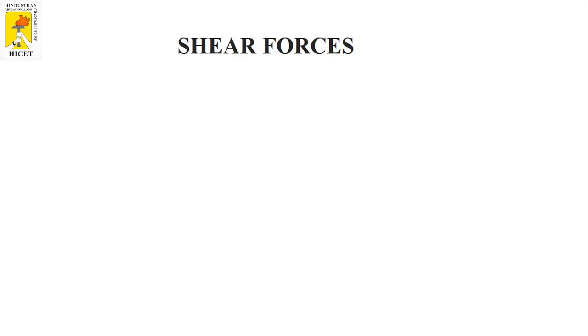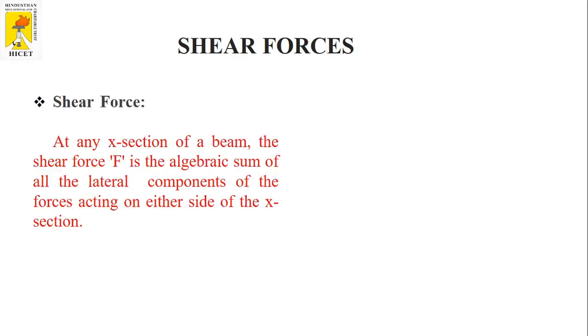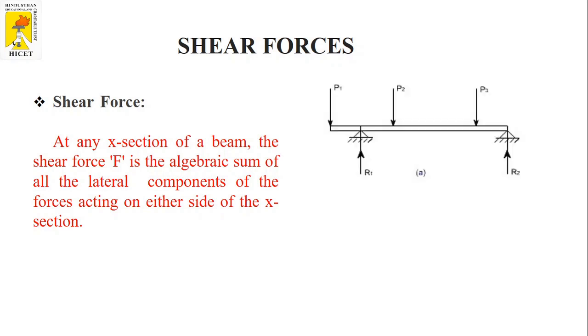Shear force. Shear force is defined as: at any x section of a beam, the shear force F is the algebraic sum of all the lateral components of the forces acting on either side of this x section. So let us see an example of an overhanging beam.